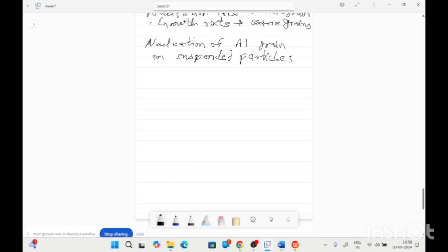Generally in aluminium alloys, titanium powder is added for heterogeneous nucleation. The titanium will react with the aluminium and form an intermetallic Al3Ti. The melting temperature of this intermetallic is very high, so it does not dissolve in the melt and provides a heterogeneous site.